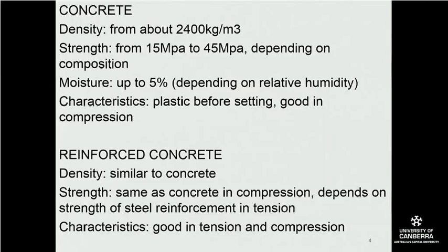The disadvantages of concrete are that it has a little bit of shrinkage, which may cause a little bit of cracking. Cracking is bad in certain circumstances, not so much for strength, but more for water incursion, which I'll talk about a bit later on. Not everybody likes a lovely grey color of concrete, and the concrete products that come bagged up have limited lifespan, so they tend to solidify by themselves in certain environments, especially environments which have a little humidity.